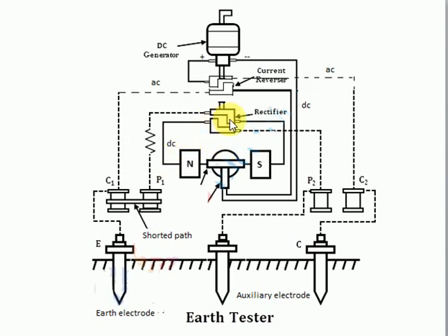Now we can see here the pressure coil. This AC current again is converted into DC with the help of this rectifier, and this is connected like this. It is connected to ground, and this pressure coil is actually placed across these two poles N and S, and this side represents the output which is now converted, which is DC. So this is connected across the rectifier as well as across the ground with the help of the rectifier.